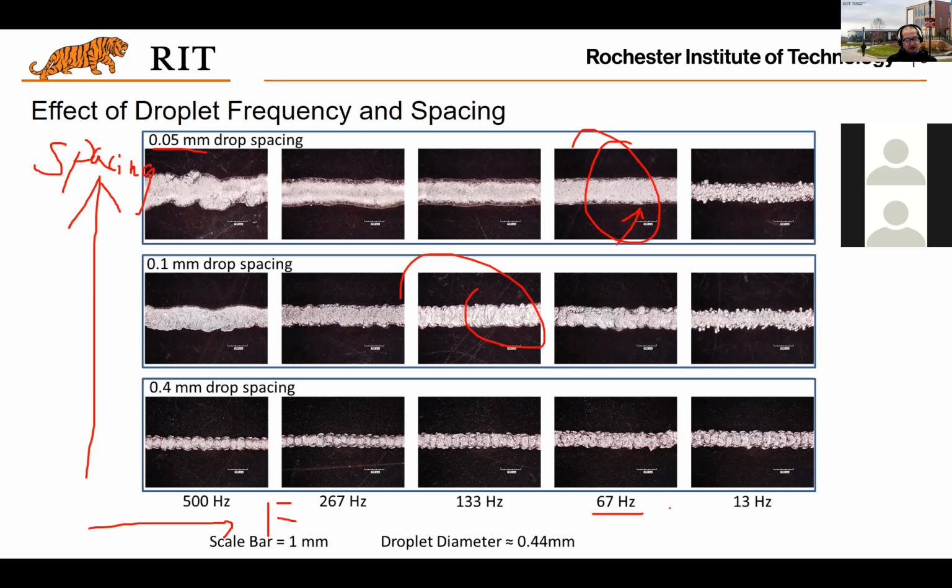So this is the design of experiment. You want to find some parameters and do some sampling in a range for those parameters, and make sure to cover combinations of all these sampled values of the parameters. And it turns out you will have a span of the parameter space versus some printing results. And among these results, you will find the best one. That is how you determine what kind of parameters you should choose.